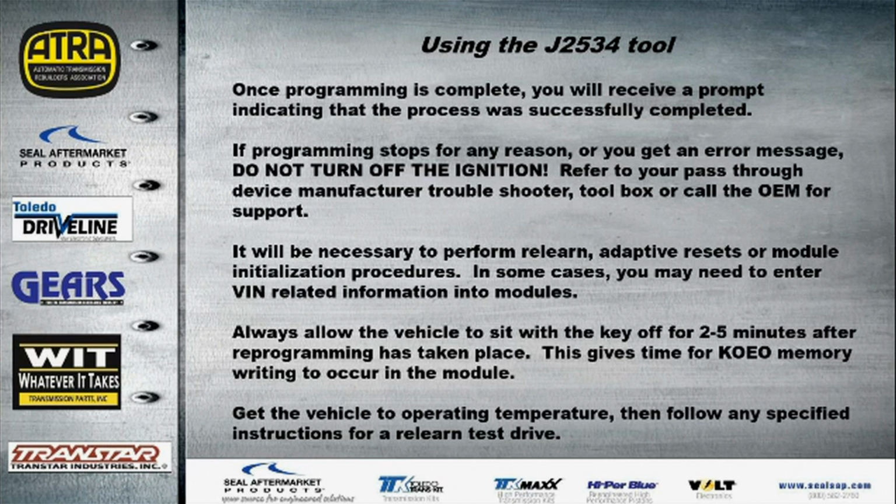Now, after we programmed, if we were successful, we'll be at the next step. It'll be necessary to perform a relearn or adaptive resets, module initializations, and other types of resets, like maybe the throttle actuator control motor reset. Some type of reset is going to have to take place, and we're going to have to make sure that we perform all of those before we go any further. So just to keep that in mind.